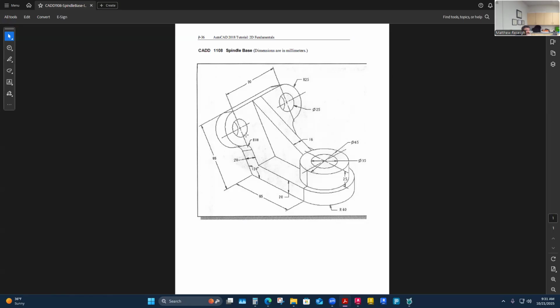What an ellipse needs generally is what we call major and minor axes. Like an oval has a longer and a shorter width. It might have a major that's longer in one direction, and the minor is shorter. If we were to draw center lines through a circle, they're all the same, right? When I'm looking flat on a circle and I divide it into quadrants, same length. Well, not so when you look at a distorted circle. It's going to look like an ellipse.